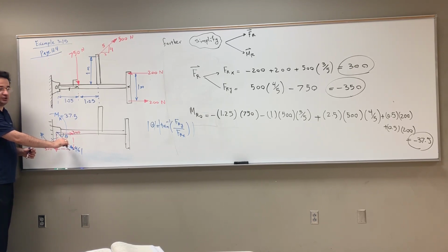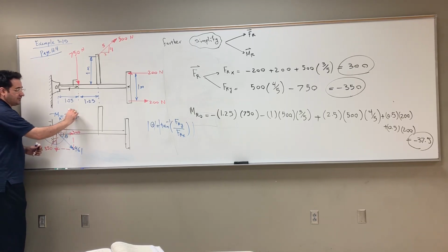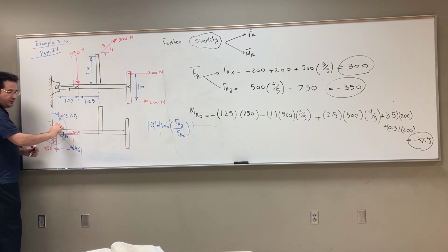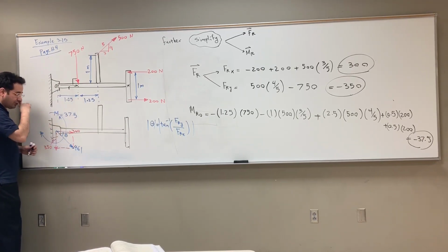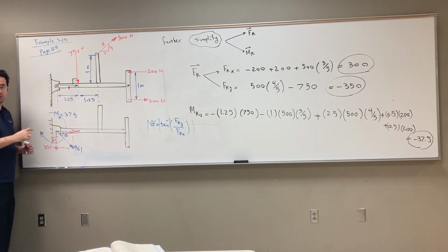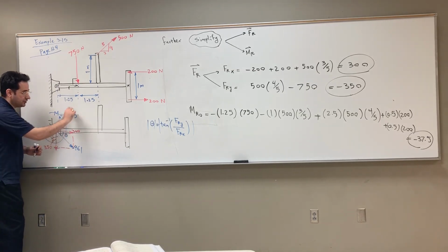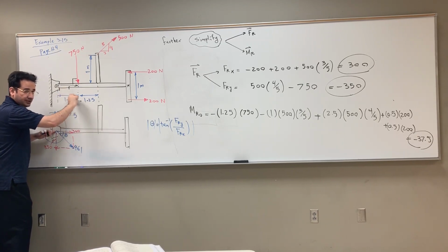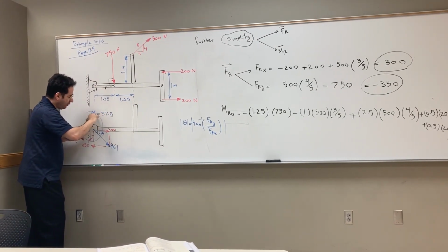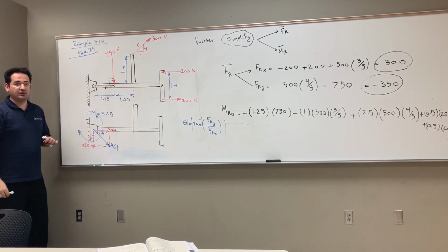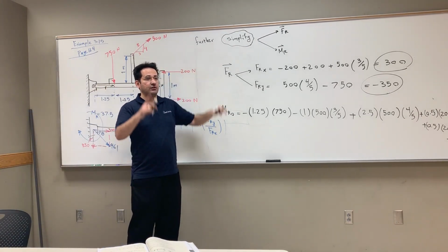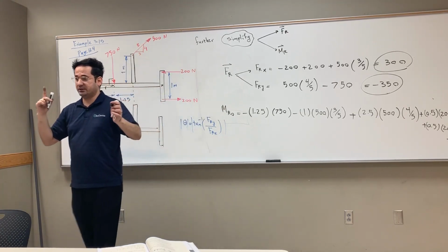Now, if we move a force sideways, perpendicular to this angle theta, such that this single force by itself can generate this moment, then I can just ignore this moment, and at the end I will have just one force at a particular distance acting along a particular line that also generates that resulting moment effect. So I can further simplify the system with just one force instead of one force and moment, right?